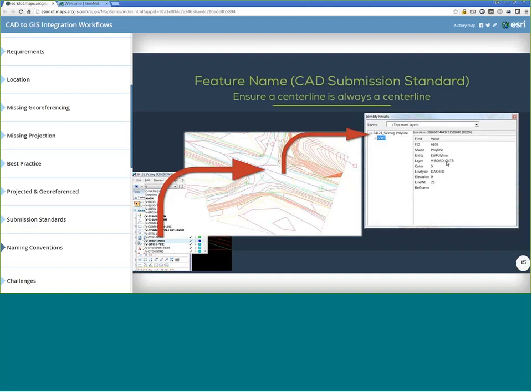That's not the issue. The issue is when I've got another CAD file where maybe they spell center instead of CNTR, or DRIVE instead of DRIV, or some other derivation of that layer name. That's when I run into problems. Generally, if it's missing, that's not as big a deal, but when it's a different name, that's a big deal, because I'm using queries to extract out these layers.